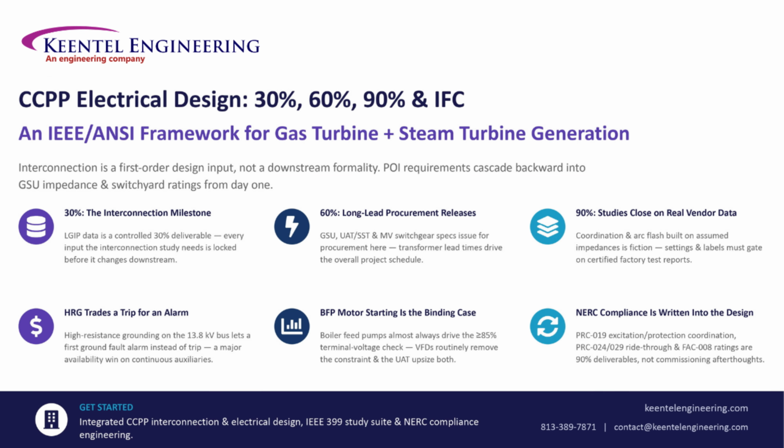Let's close out on why combined cycle plant design has to be interconnection first. The point of interconnection isn't a downstream utility formality. Its requirements cascade backward into GSU impedance, generator capability curves, and switchyard breaker ratings. That's why the interconnection basis gets anchored at 30%, with the LGIP data submission treated as a controlled deliverable with the same rigor as the one-line diagram itself.